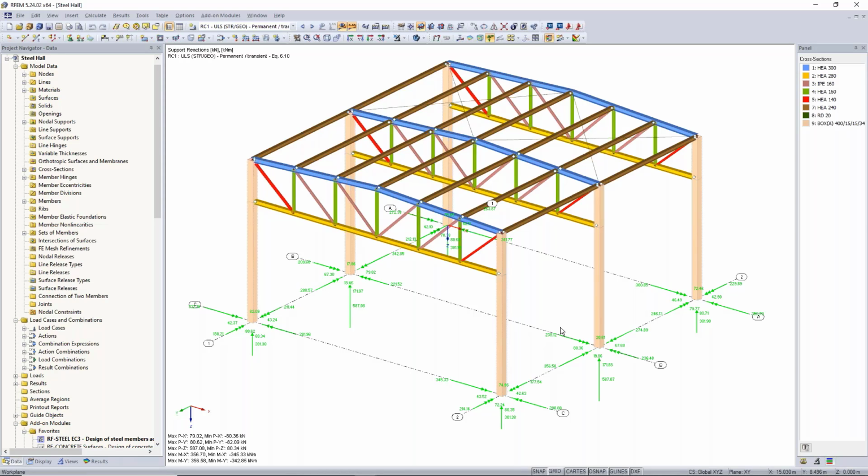If I would change something, let's say on the girder or the column, I would also lose the results for my foundation slab. If I separate these structures, the steel hall and the foundation plate, into two individual files, then the benefit is that the calculation time for each individual part of the structure is not so long.